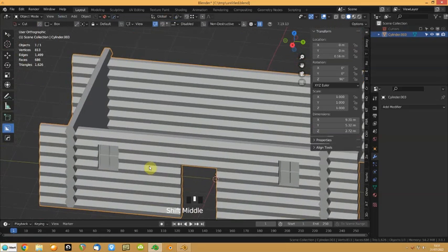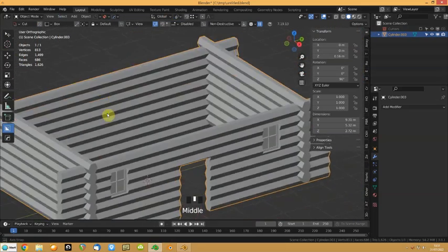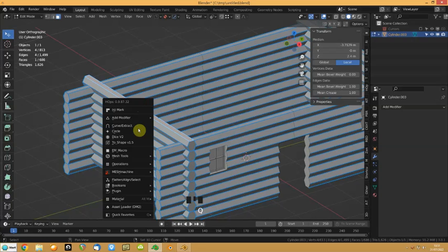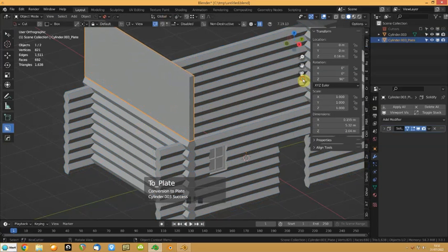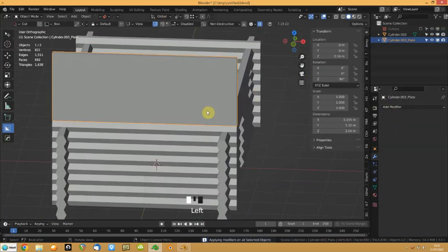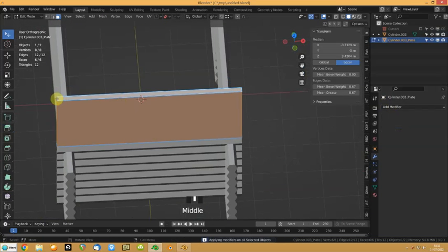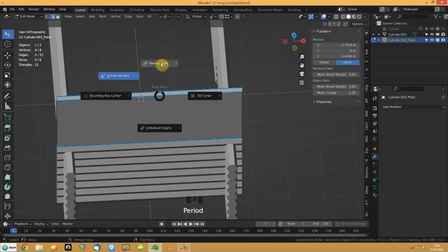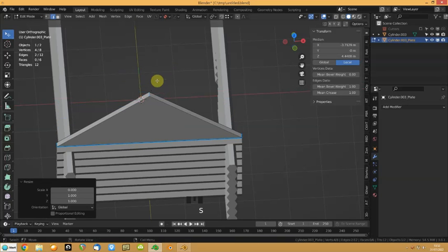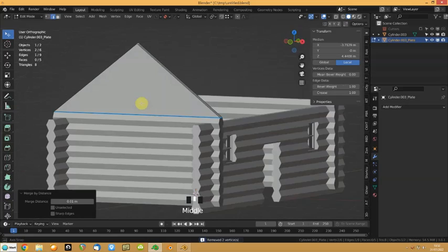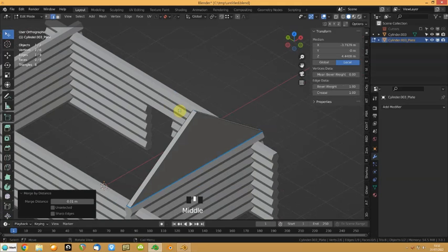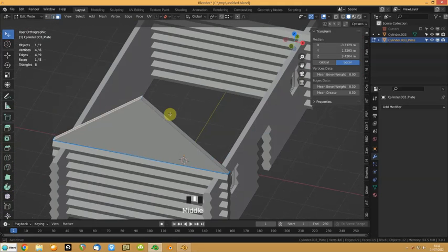Another thing you can do is if I wanted to create a gable end here, I can come in here, I can select that face, Q, Shift Curve Extract, and then I can just take these two edges, scale X0, make sure I'm at medium point, scale X0, merge B, and there we are, gable end, quickly done. Very handy.